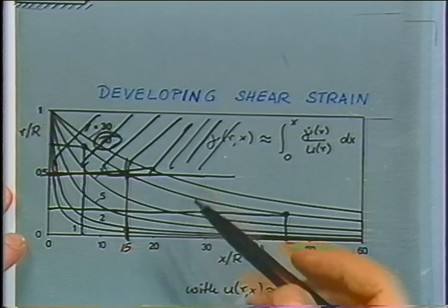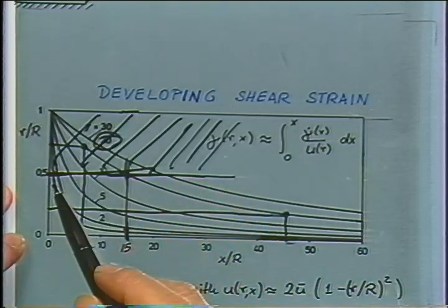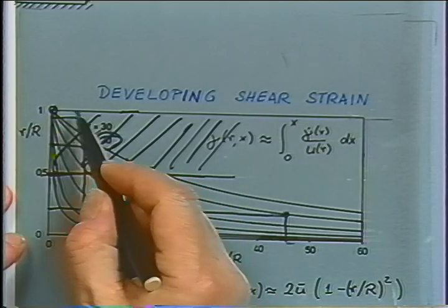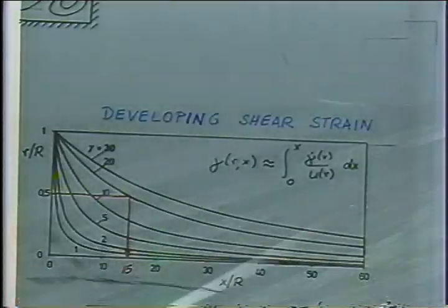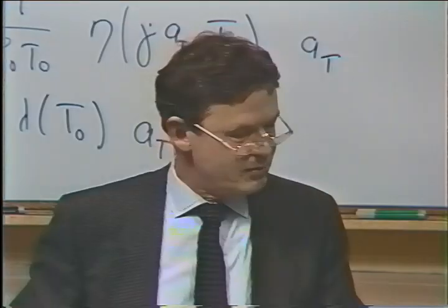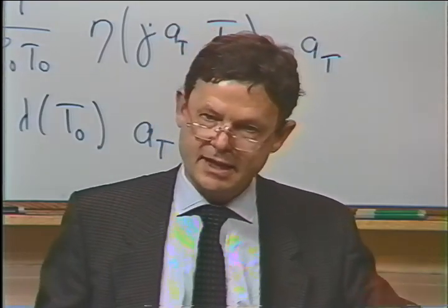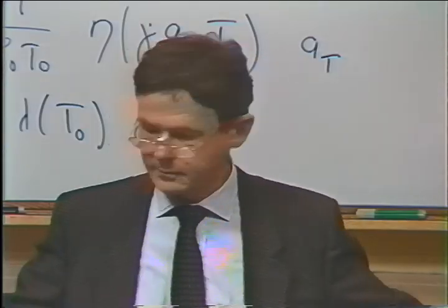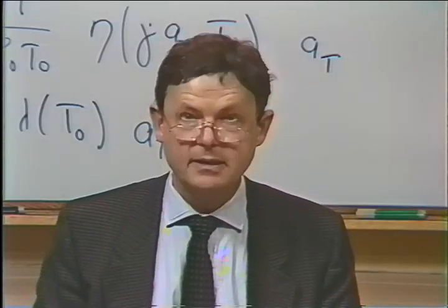So our measurement is okay because we are reaching steady shear flow in this outer region. And that is associated with this example that for any channel at the wall, you immediately reach steady shear flow when the material enters the capillary. But when you have a finite layer thickness, you need a finite length to reach steady shear flow. Okay? So that is what we call the rheological development in the stress on a material element moving through the capillary. And we assume that the stress is fully developed.